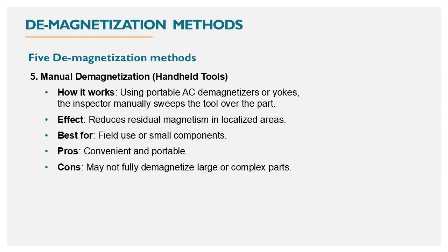This method is best for field use or small components. The advantage of this method is that it is convenient and portable. The limitation of this method is that it may not fully demagnetize large or complex parts.